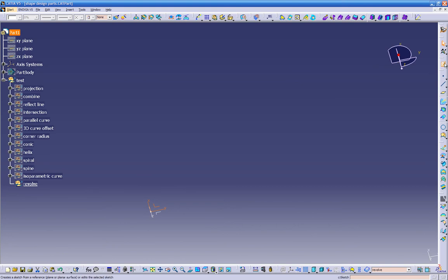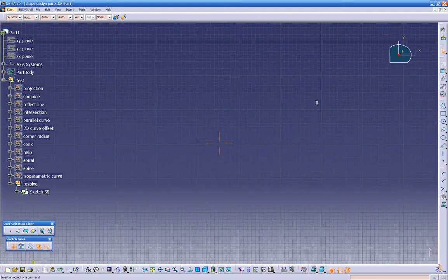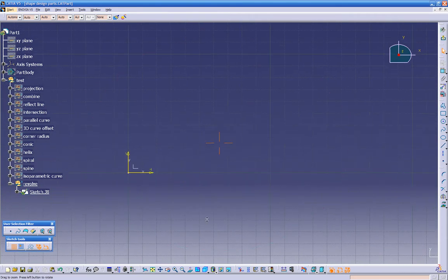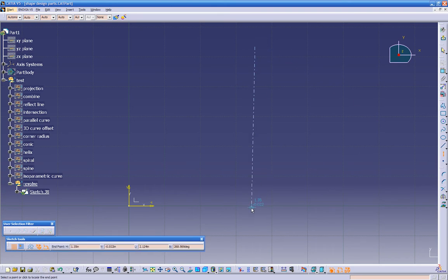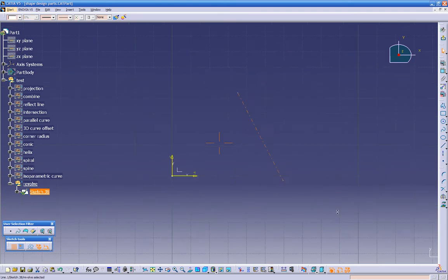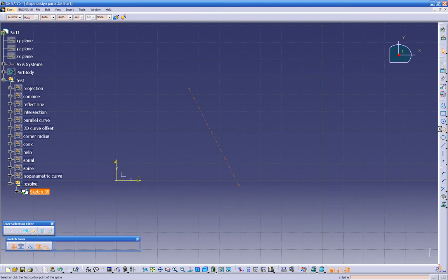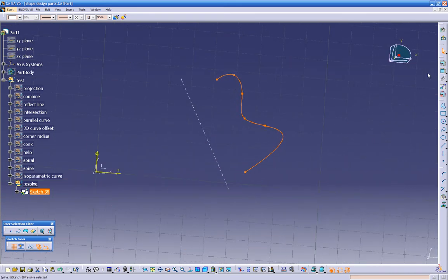Let's get a quick sketch over here. Let's create an axis. It doesn't have to be perpendicular. Let's create a weird shape axis, because I got some guys that were working for me, and I would show them how to use those options, and they always think that axes always have to be perpendicular to the surface. I mean, to your plane. It doesn't have to be necessarily perpendicular. It's an axis. You can build it however you want.